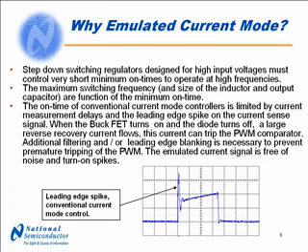Step-down switching regulators designed for high input voltages must control very short minimum on times to operate at high frequencies. The maximum switching frequency and the size of the inductor and the output capacitor are a function of the frequency, which is forced by the minimum on time.